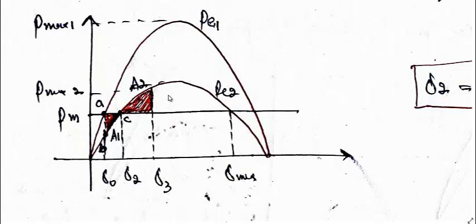But definitely there is a good amount of area available, so we have assumed the system will be stable in this case. You can see it here. So it swings forward from point B, C, let us say this is D, then D, C, and A. And in this case, since the system is stable, this area will be equal to this area.